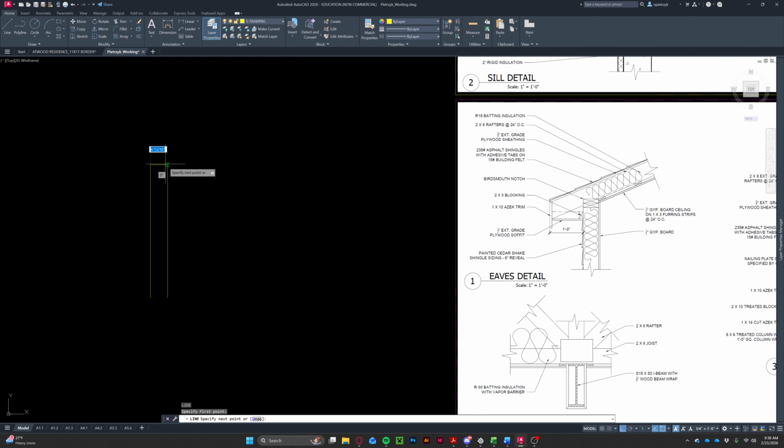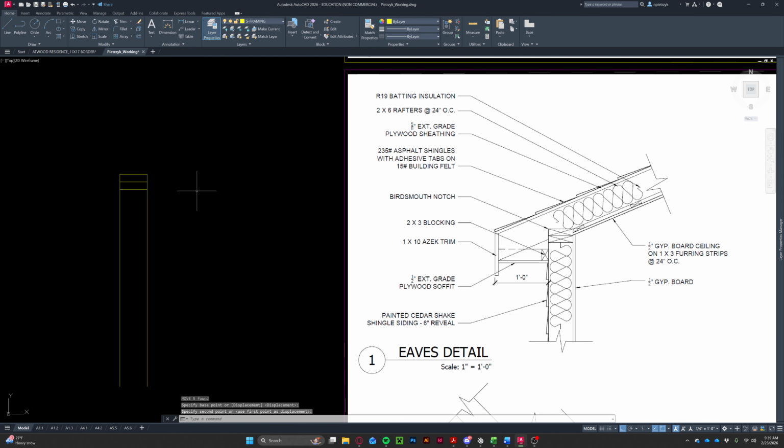I'm going to draw a line across the top because I need to do this double top plate. And this is 2 pieces of lumber running along the top. So I'm going to offset 1.5 inches because it's 2 2x6s at the top, like so. And I may even just move this in a little bit more and zoom in a little bit more. There we go. And I'm going to create X's in these to denote these being sectional lumber here.